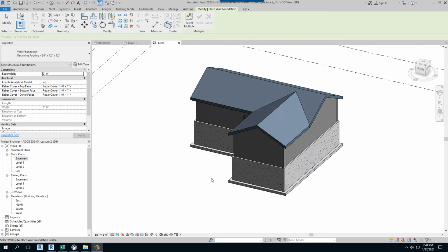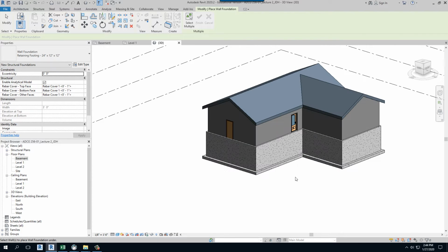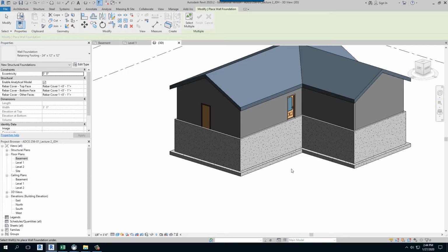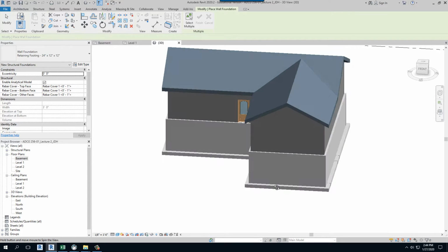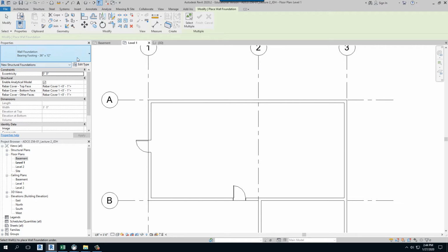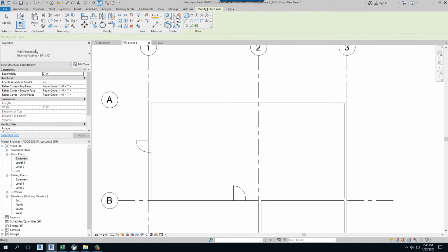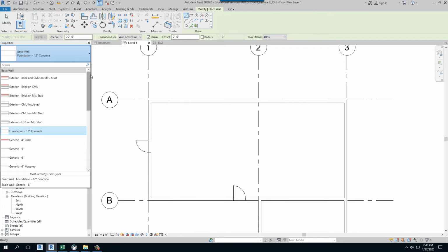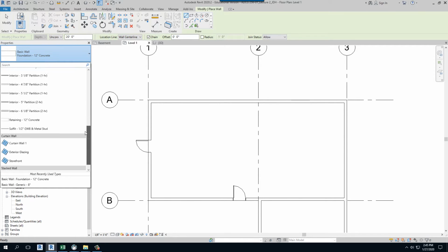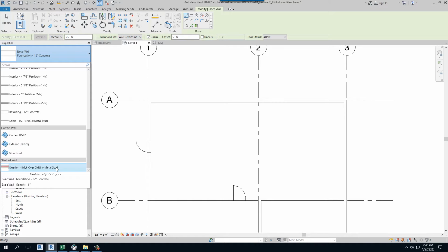So you remember we were talking about our walls being somewhat generic, okay? Yes, they are very generic. Let's say we wanted to put a material out there. Now we know Revit comes with some pre-made walls, right? If we go to the architecture tab and go to wall architectural, notice there are several pre-made walls we can use. One of them is called a stacked wall.